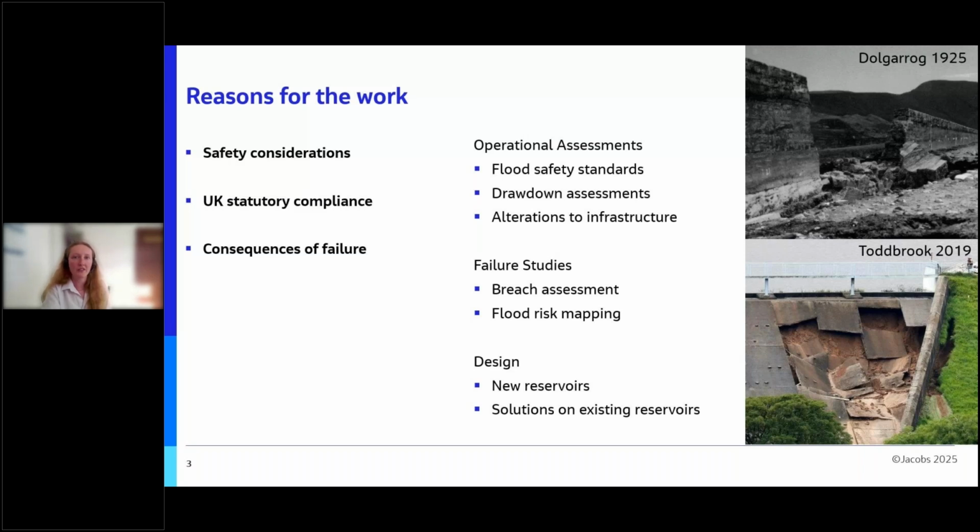Flood studies are interested in identifying still water freeboard and wave overtopping discharge to determine whether the overflow facilities are suitable for passing the 10,000-year design flood and the PMF safety check flood. Peak outflow is a key output from these flood studies, and these then feed into assessment of overflow performance.